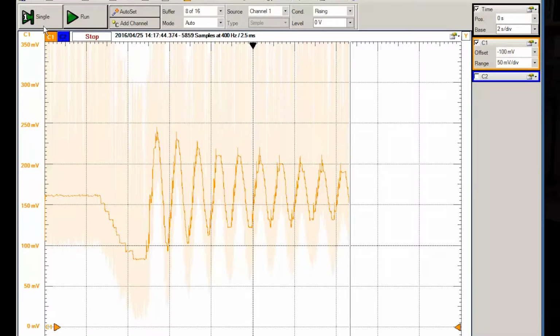If the entire range of motion is about 15 inches, this means that the sensitivity is about 0.2 divided by 15, or a little over 1/100th of a volt per inch. This will make it hard to actually measure small displacements since the related voltages will be so small.